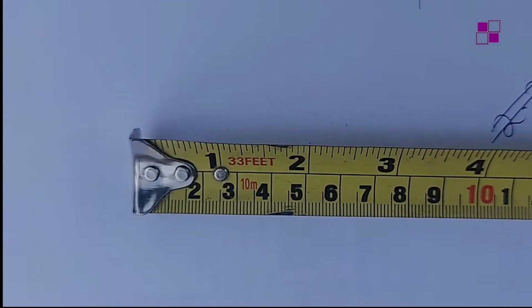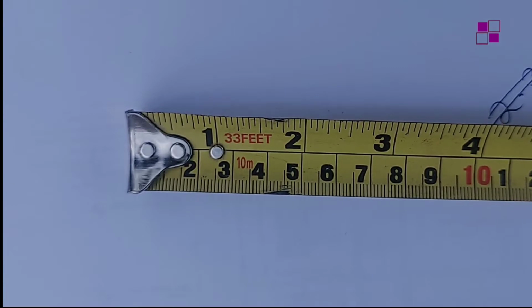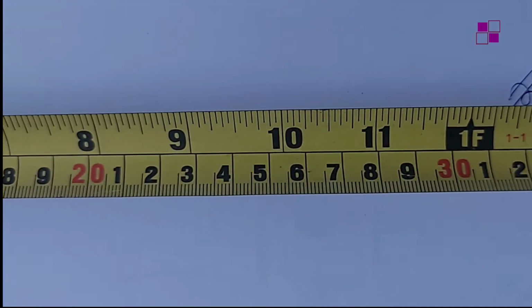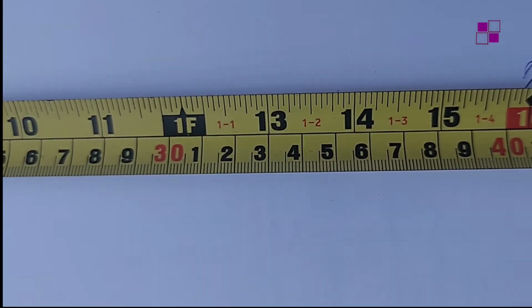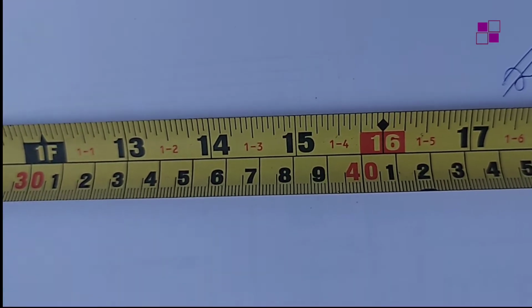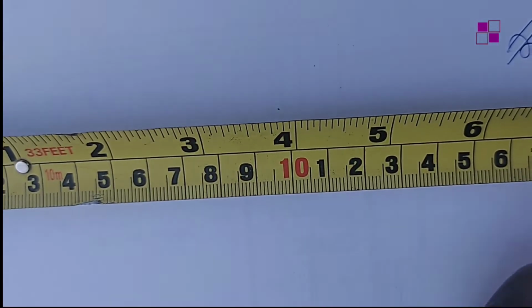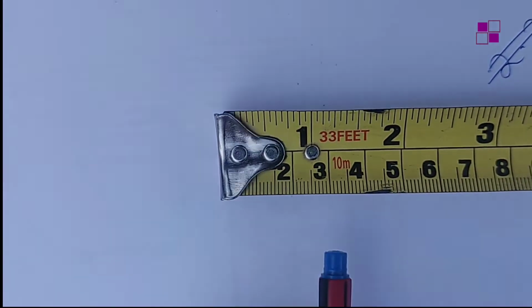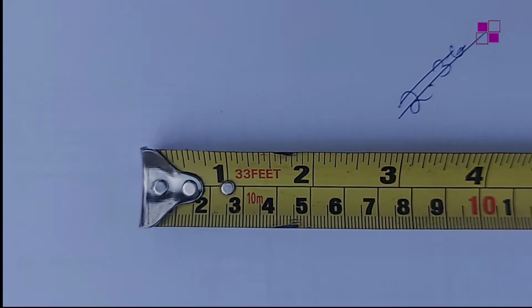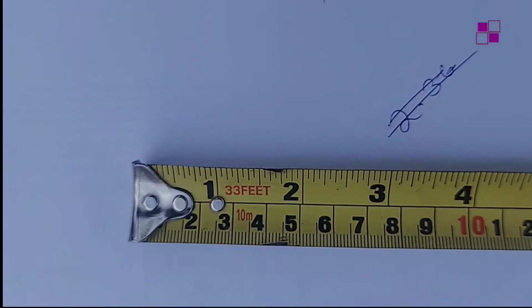But the deceiving part of the measuring tape is this. This part is measured in centimeters. This is 10 centimeters. This is 20 centimeters. If you continue like that, if you have a small plastic measuring tape in your math set or something, use it to measure and confirm what I'm telling you. So all these measurements here are in centimeters, yet it is written here that it is a 10-meter tape. That means if you must use this tape, you have to do some little conversion while you take your reading. Don't worry, I'll put you through all that.